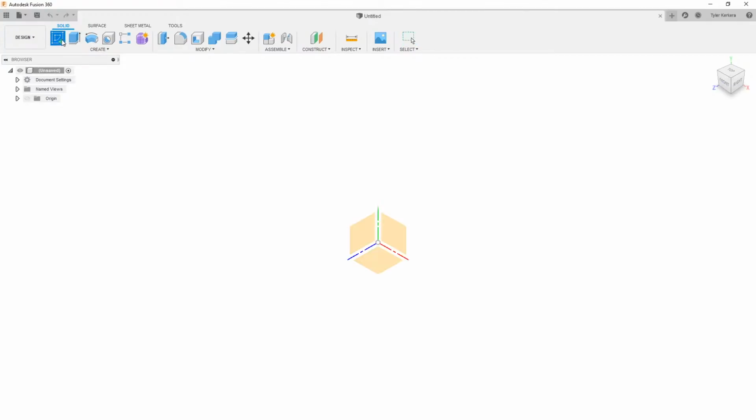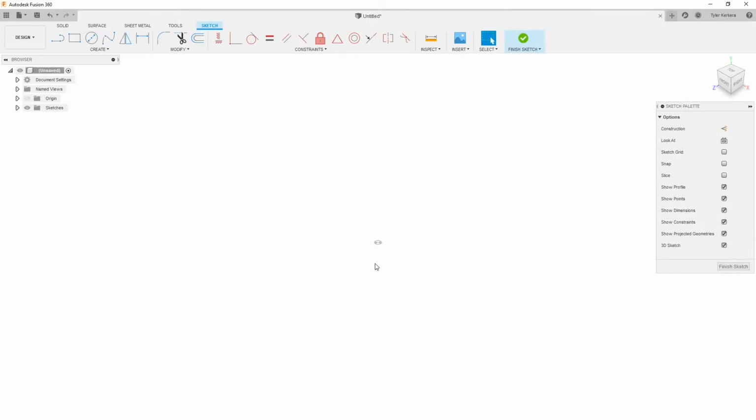So it's as simple as just pulling up a 2D sketch, selecting a plane as you normally would, but on your sketch palette here, you have something called 3D Sketch. And this necessarily isn't new. This used to be here before too, but we'll want to make sure that this is engaged or selected. From here, I'm going to start drawing lines, and that looks a little bit different. So they'll refer to this as that triad.